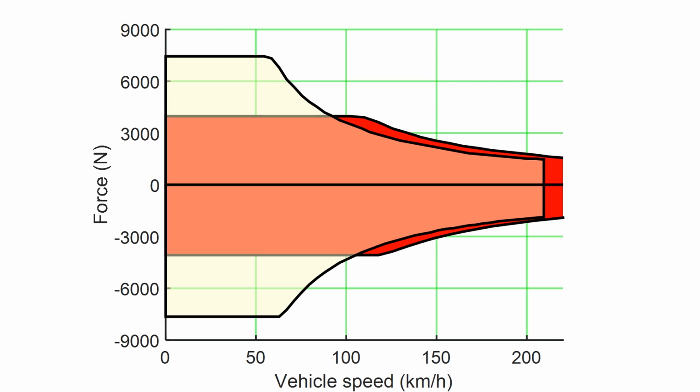Still, what looks like small improvements in force between 100 and 200 km per hour still are in the order of a 20% increase in force. So it can either provide that much more performance or allow the electric machine to be made that much smaller. The reason why an additional gear could increase the force is that the electric machine could not keep the peak power as the speed increased.